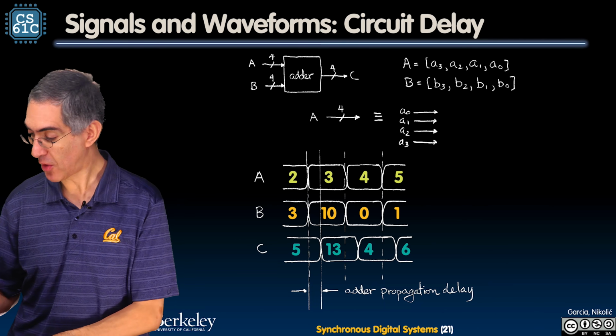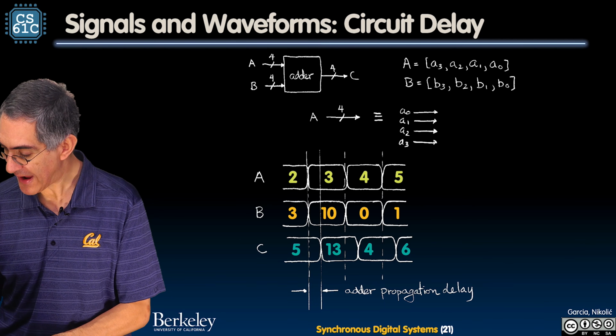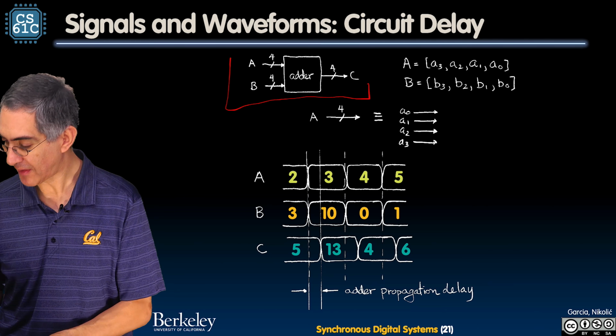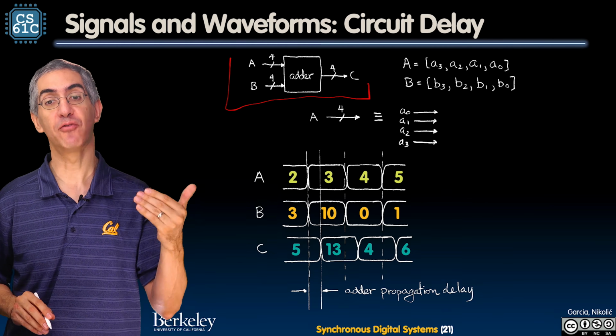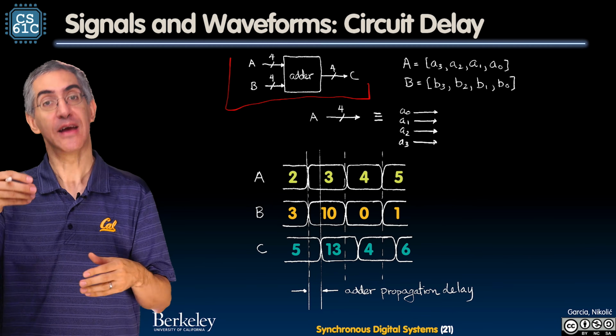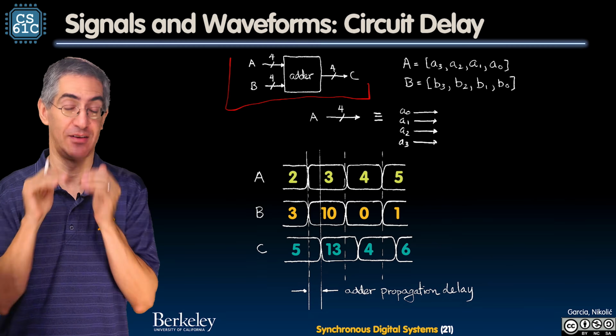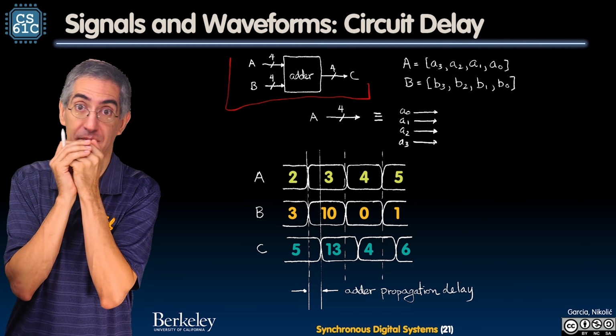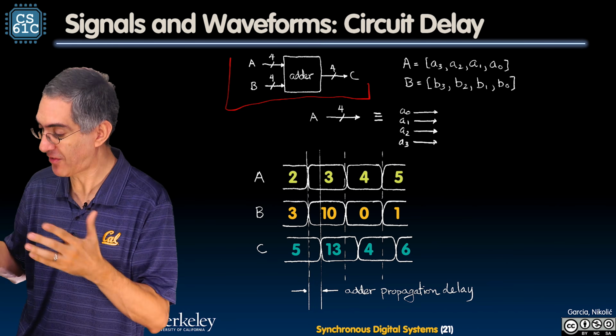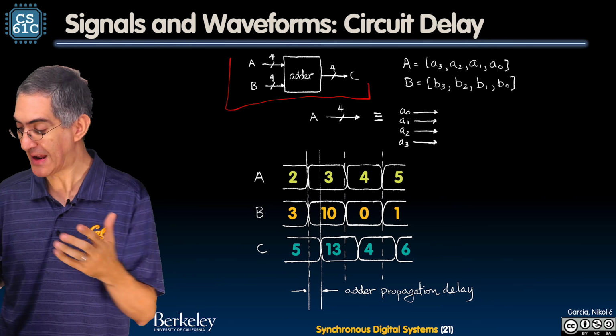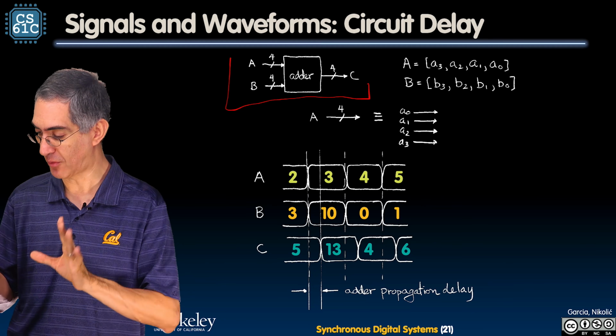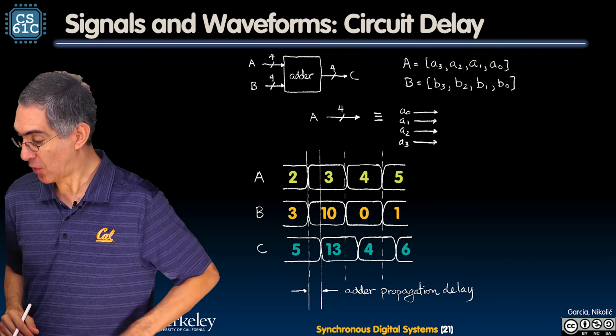Now here we go, an adder. This is called a nibble adder. Look at that. 4 bits of A come in, 4 bits of B come in, and A plus B is represented on the output C. Sometimes 4 bits can't be enough to do that. That's when overflow would happen. But for now, let's pretend that overflow isn't happening, and A and B are going to be small enough that there's no overflow. So that's what we got. This is fine. So that's pretty cool.